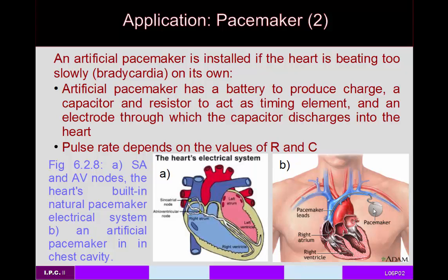Incidentally, by adjusting the capacitance, you also adjust what the total charge is going to be. So there's a little more engineering to this than just picking a random value of R and C. You need to have C such that you get the right amount of charge, and then you can adjust R to get the right timing for the charge.